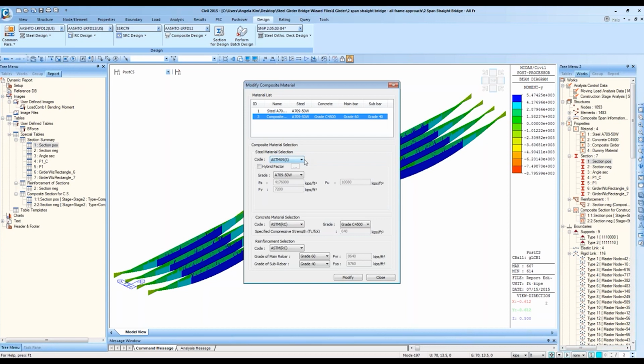But it's not the case if you are doing any plate modeling, like if the plate is involved for the deck or the entire girder or just for the web section, whatever the case may be, if it's no longer just one beam, you do not have to worry about it. But in order to get to the design portion, you need the grillage analysis approach.